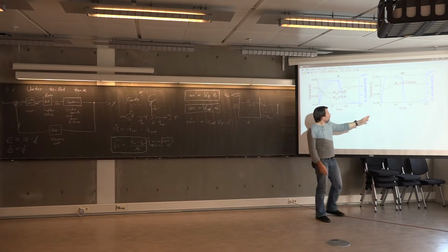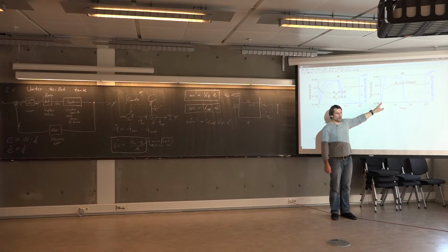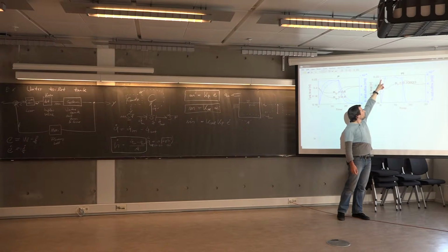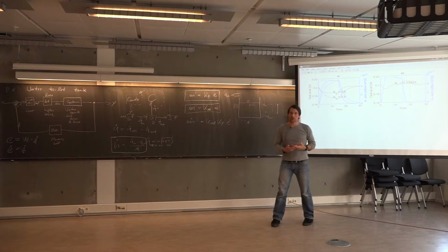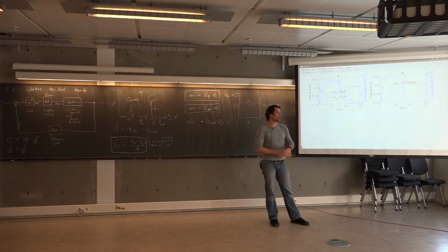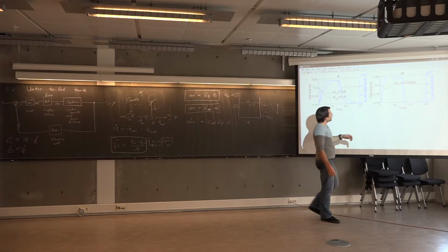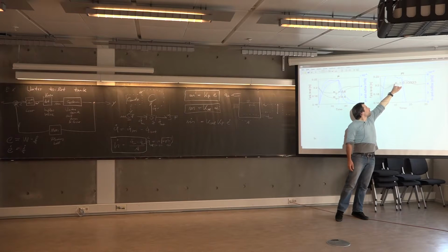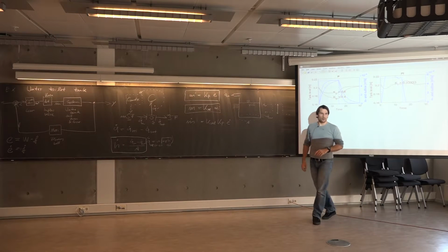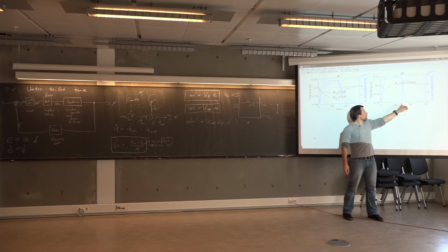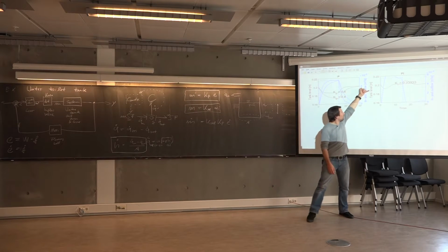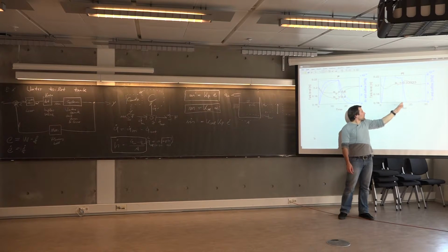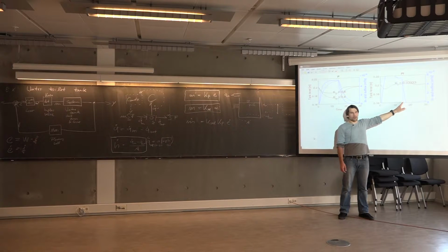We have the very same outflow profile again. At 0.5 seconds someone presses the button, there's a certain outflow. And over time, this controller now, due to the additional integral control behavior, is actually able to get rid of this error. There is some dynamics here, right? It sort of slightly oscillates if we use a much longer time now with these numerical values. It would eventually level out at the reference level at 0.2. But here the outflow is set to 0 again after 15 seconds.